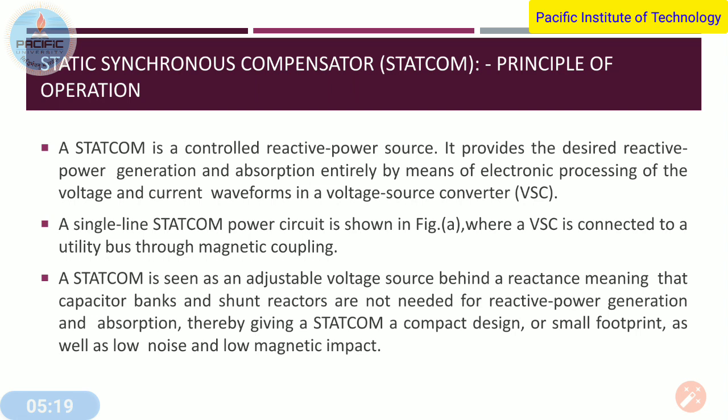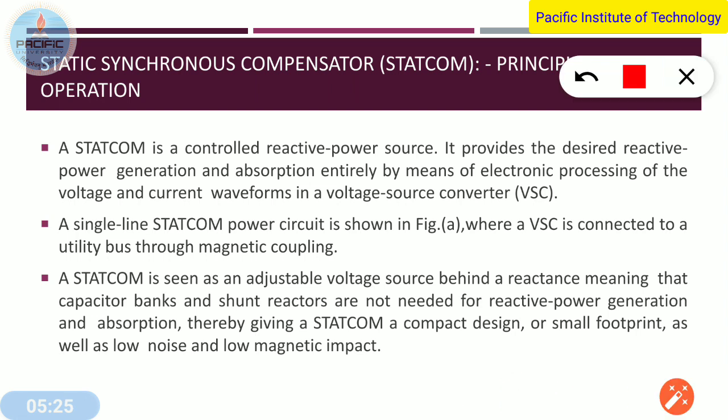Now, what is the principle of operation of a STATCOM? Right? We already discussed it in the last figure, but here we'll discuss it again. So STATCOM is a controlled reactive power source. It provides the desired reactive power generation and absorption entirely by means of electronic processing of the voltage and current waveform in a voltage source converter. So, first thing is clear that the STATCOM is a controlled reactive power source. It can be controlled by controlling the voltage source converter, right?